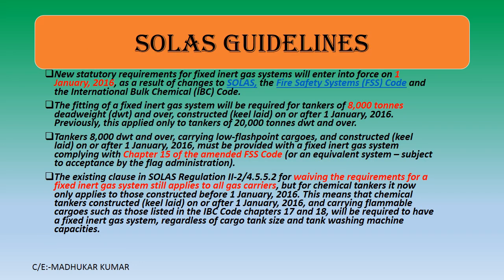As we are going to see about the SOLAS guideline, or you can say as per the FSS code and the IBC code. Okay, so the fitting of the fixed inert gas system is required for the tankers of 8,000 tons deadweight and over constructed on or after 1st January 2016. Previously, it was applied to the tankers of 20,000 tons deadweight and over. So now tankers of 8,000 deadweight and over carrying low flashpoint cargoes and constructed keel laid after 1st January 2016 must be provided with a fixed inert gas system. That is your chapter 15 of the FSS code. Okay, in that one it is incorporated.